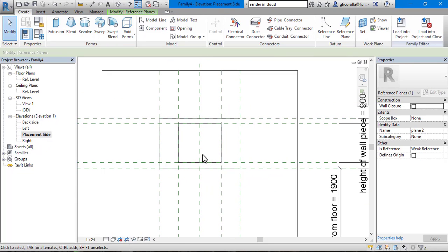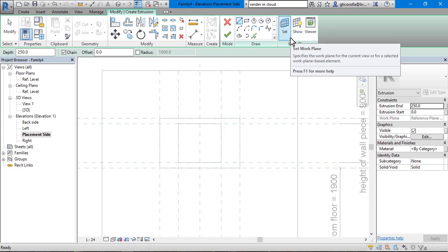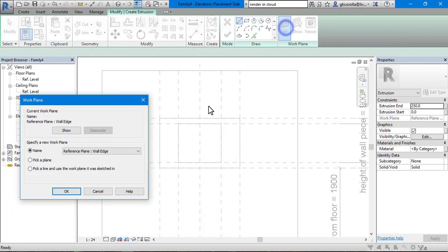So what we're basically going to do is create our sun rays image on this square here. So we click Create, and then Extrude. We're going to set our surface to plane 2, because we don't want to be drawing on the back anymore.